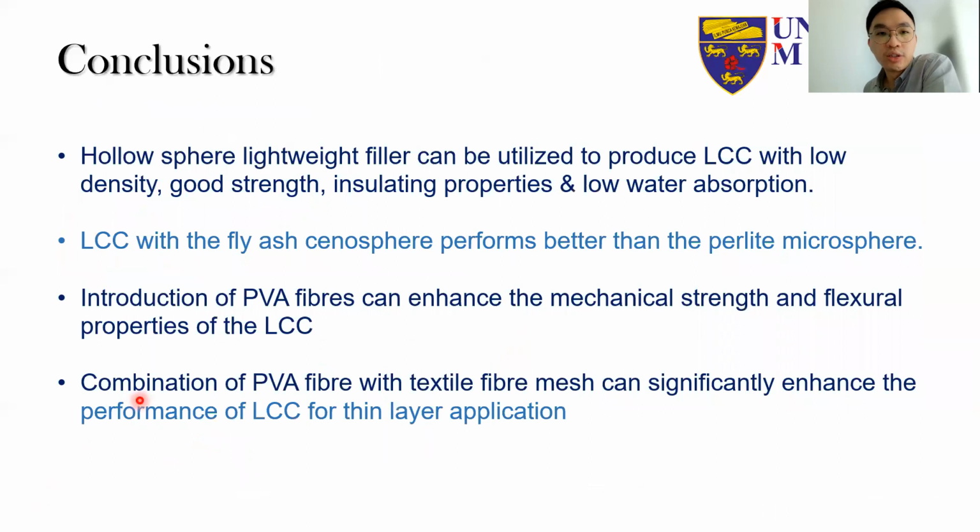So in conclusion, what we can get from this research is that with the hollow sphere lightweight filler, we can produce LCC with low density. It depends on the density that you're targeting. It can go below 1000 kg per cubic meter, or it can be slightly above 1000 kg per cubic meter, but still having very good strength.